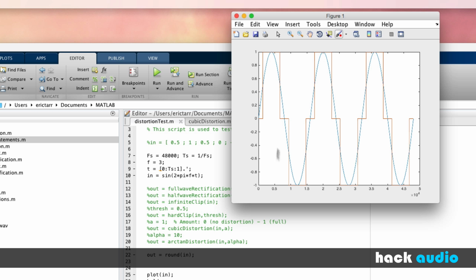Same thing when we look at negative numbers. When our input signal is 0 down to -0.5, it gets rounded up to 0. And then when we have -0.5 down to -1, our output signal has a value of -1. So in this case, we've produced a signal that really just has 3 possible amplitude levels. We're getting closer to the concept of what bit reduction is all about.